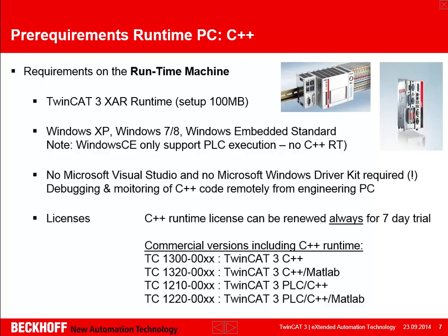And then you need the TwinCAT 3 XR runtime. It's a setup of about 100 megabyte because, well, it's just a runtime. It is not the engineering environment, to save space. Definitely at the machine you normally do not need the Windows driver kit and the full Visual Studio, because you do debugging and monitoring remotely from the engineering PC.